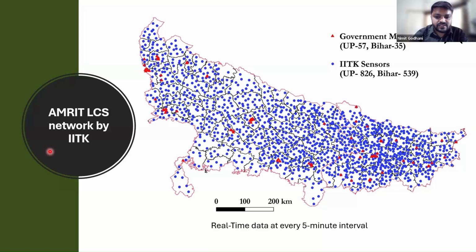The Vaisala instrument is there for the reference. So what we do is compare the temperature and humidity also. We first correct the temperature and humidity by point-to-point measurement, with quite good results. Then for each point of 1 degree of temperature and 2 or 3 percent of humidity, we put some intervals and make a correlation matrix.